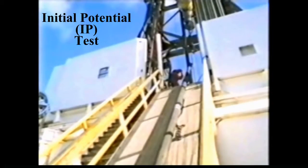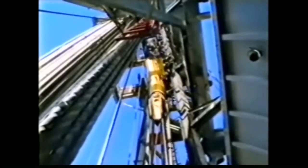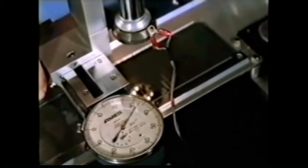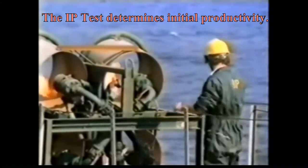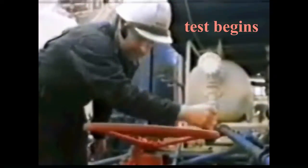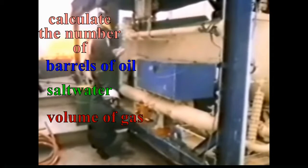Finally, the last test, the initial potential IP test, is conducted after the well has been completed and equipped in what is known as cased hole or closed hole, but before the well has been prepared for production. This very important test allows reservoir fluid volume or flow rates and pressure measurements to be accurately determined. The initial potential test, IP, determines the initial productivity and is done over a period of from 24 to 36 hours to calculate the numbers of barrels of oil, of salt water, and the volume of gas that can be produced during this 24 to 36 hour period.